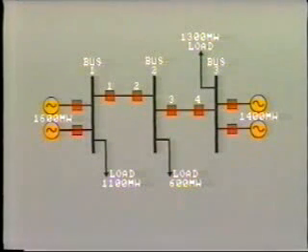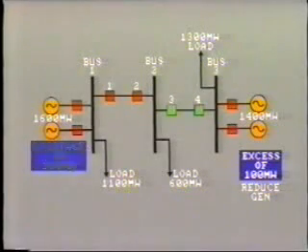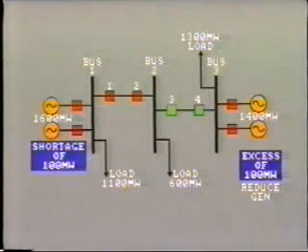So we have learned that where out-of-step conditions do exist, the systems must be separated. Each separate system or island will have to be stabilized before the two can be synchronized and reconnected. However, when the systems split into islands, we may run into another problem. That is, one of the islands may have insufficient generating capacity to meet the power demand.